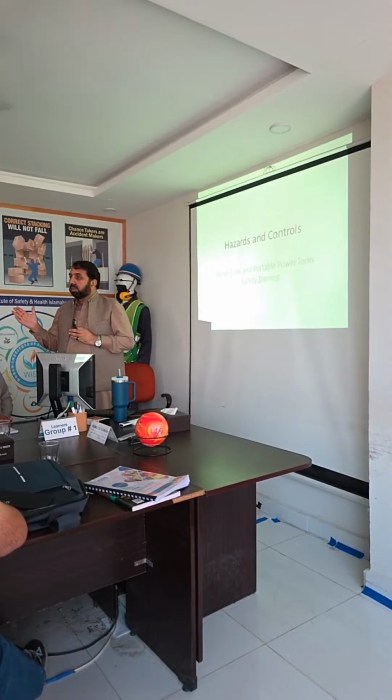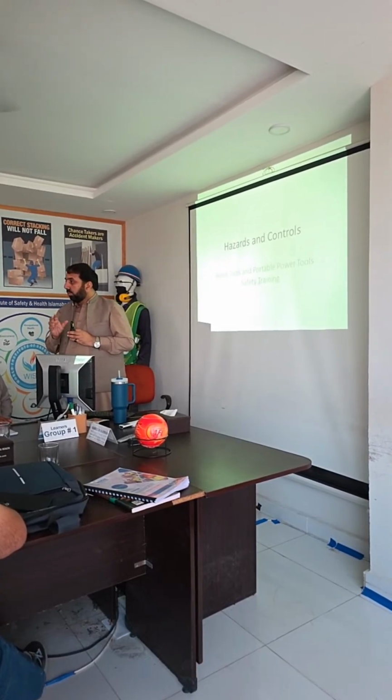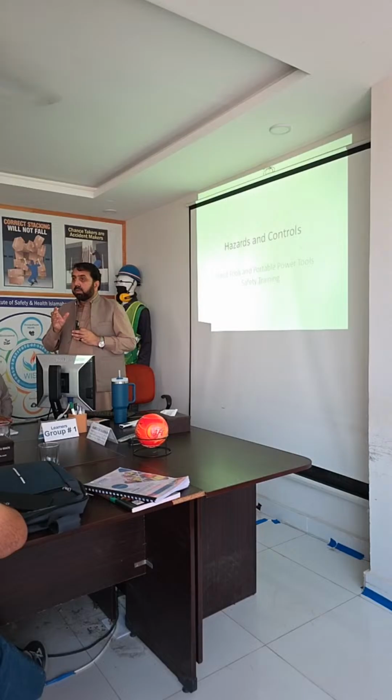And then we come to the machinery in the next slide, I think. So keep in mind, if as a safety professional you are on the site and workers are utilizing the tools, you must take proper preventive and protective measures for it. Is it okay? Yes. Workers mostly, what they did, like with a circular saw, they left the circular saw on and they left the area. And it is not properly shut off or not properly guarded.